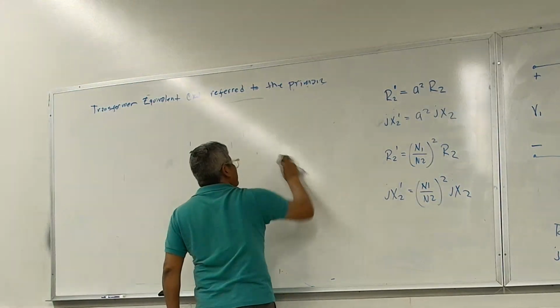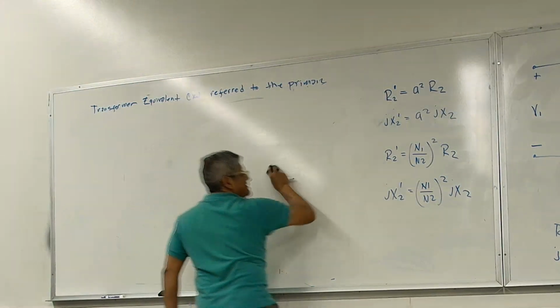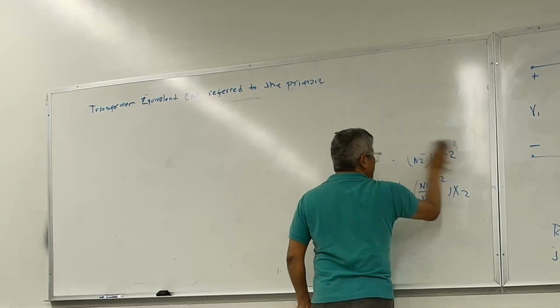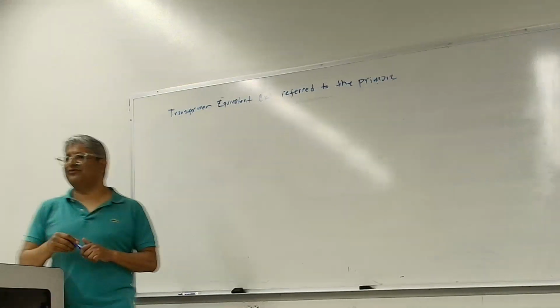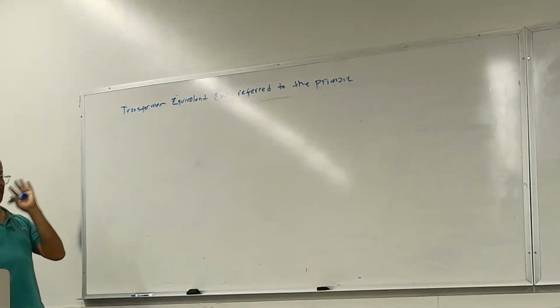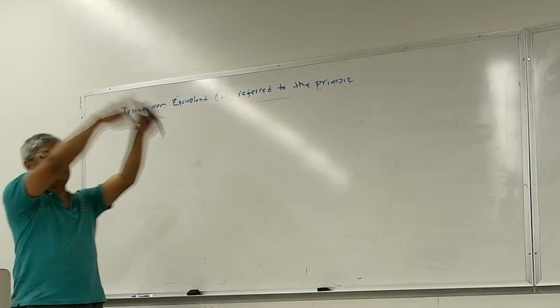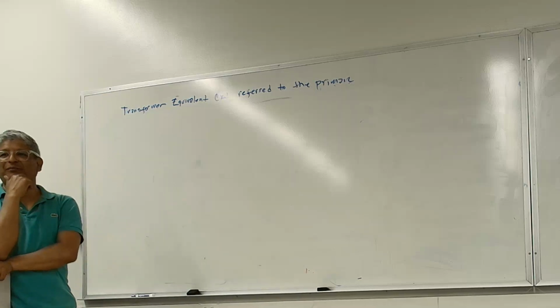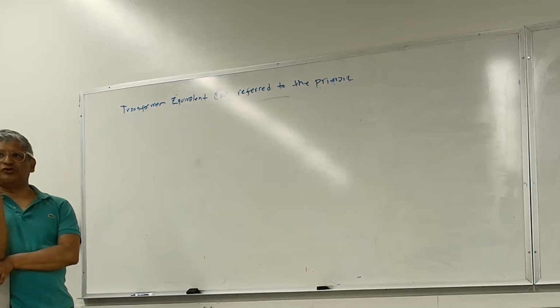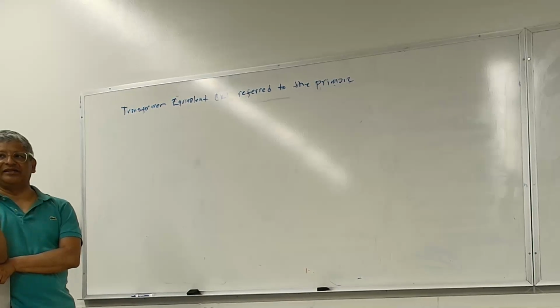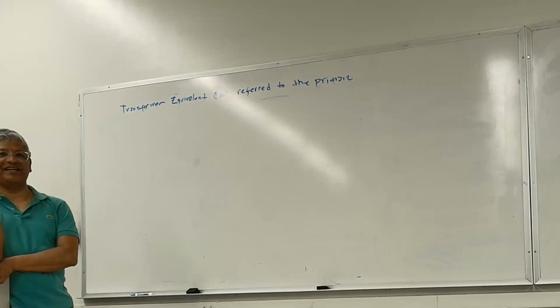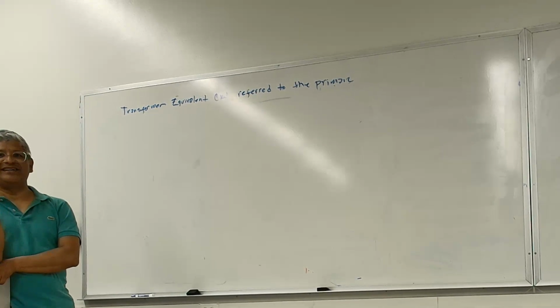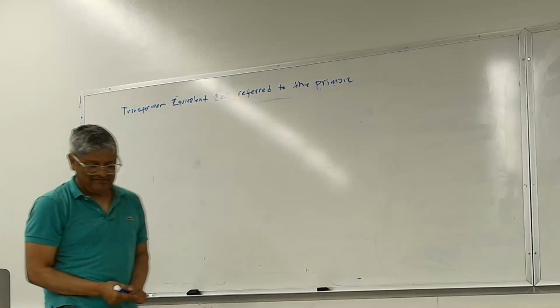How do you think we're going to treat the impedances of the transformer core and windings in order to transfer everything from the primary side to the secondary side? What do you think you're going to multiply by? You transfer from the secondary to the primary, multiply by A squared. To transfer from the primary to the secondary, what do you think? 1 over A squared. It's the inverse of that, right?